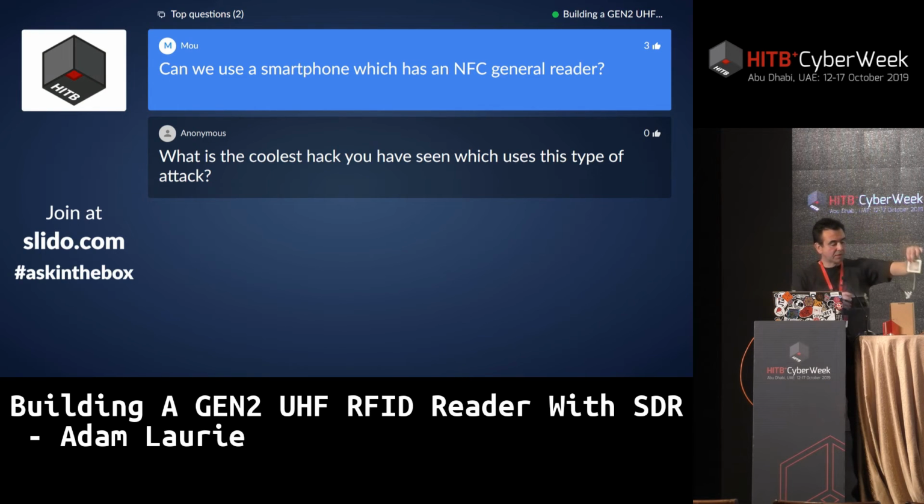The reason being, if you have a transmit and receive antenna and you crank up the amplification, you can very easily blow your receive circuit. So the nice thing about a circulator is the signal you send will not come back full strength into the receiver.